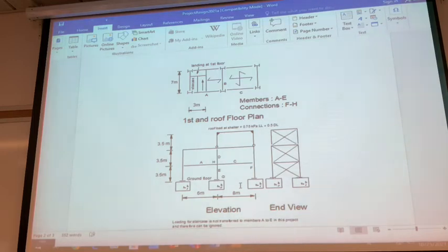This is the main beam, top flange and the bottom flange. And I will have the secondary beam. If this secondary beam is to take moment, then I need to provide a typical moment joint. So if I connect the secondary beam to the main beam, is there enough space for me to put enough bolts to take moment? And also, one row of bolts may not be enough. I may have a second row of bolts to take moment.